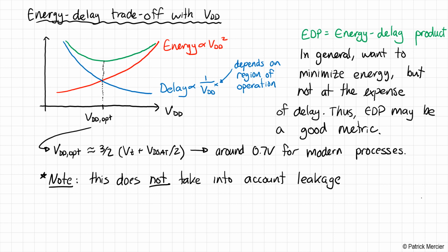And as it turns out, when we scale VDD lower, leakage power actually decreases, but the delay increases, and it increases a lot, especially when we get into the subthreshold regime. Delay increases exponentially. And although leakage power is decreasing, leakage energy per clock cycle actually increases because the clock period must increase exponentially, and therefore we're integrating more leakage power over an exponentially longer amount of time, and that results in a lot more energy.